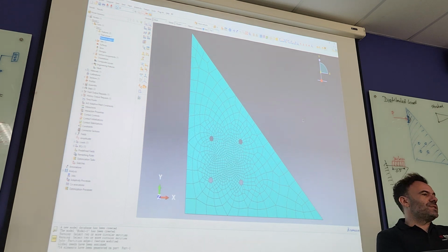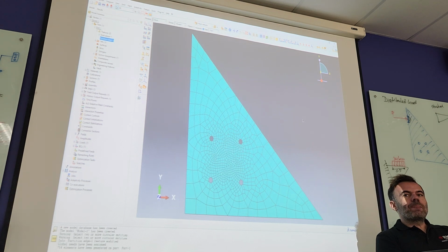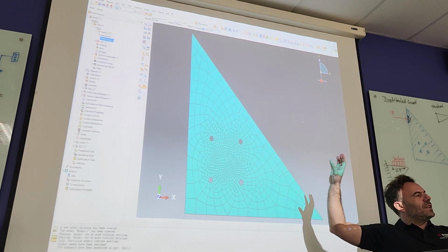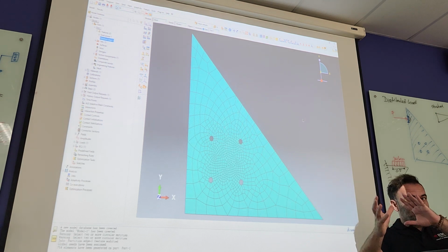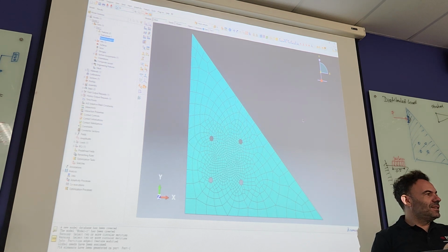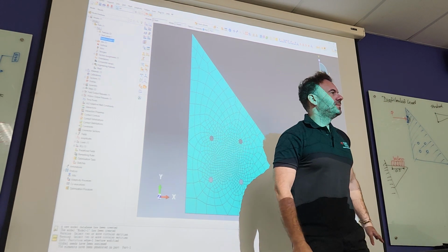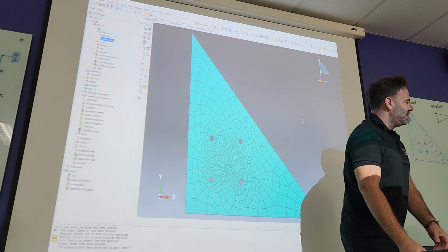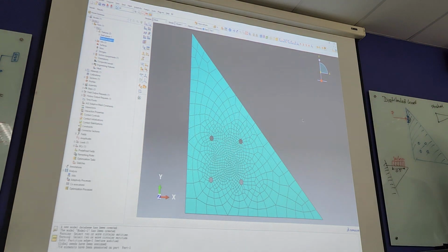But what's wrong with this mesh? Why are we not happy with this? The areas of the elements are not equal. But does it have to be? Not really, but it's best to be. Point of interest is... Yeah, so we've got two comments. We've got a point of interest there. We're also saying that not all elements are the same. That's a bad side, yeah? What else? What else is not that good about this? Or what else can we change?